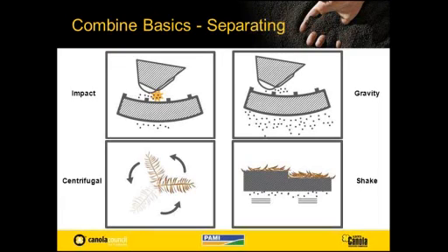Most concaves are located on the bottom of the rotor or cylinder, and again, that's to take advantage of gravity, just pulling it down. The whole need for rotary combines came about with the increased separating force that you get from the centrifugal force of spinning material around. And the smaller the circle and the faster you turn, the greater this centrifugal force, the more it wants to spin away from the center. So that's been a major force in separation.